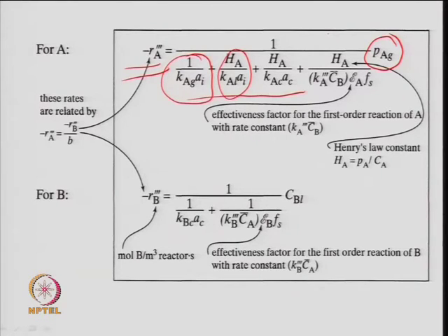So, now which step is dominating will depend whether your liquid side mass transfer coefficient is very high, or the mass transfer coefficient at the surface of the solid is very high, or this chemical reaction constant is very high. So, it means by having a suitable temperature, right, by selecting a proper catalyst size, these two can be controlled. So, you have a good kind of catalyst particle size, diffusion is one, porosity of the particle, and kinetics is there. So, temperature of the particle. So, resistances can be controlled.